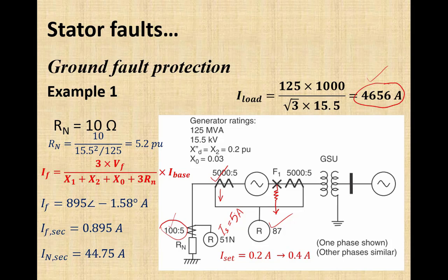But in case of very high grounding resistance, where fault current has been limited to a very low value, phase fault relay may fail to detect this fault. But we can still provide a very sensitive protection by connecting a CT and its associated time delay overcurrent relay in the neutral circuit that we have seen here in this example.